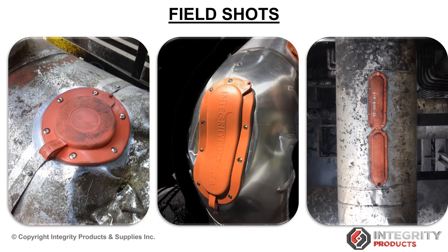I think certainly a lot of care needs to be put into the inspection port selection, because many asset owners have told us that it's one of the high-risk water ingress points if it's not correct. And we've also seen some traditional ports that are available in the market that just don't have a great temperature range. So if it gets too cold, the cover will shrink.